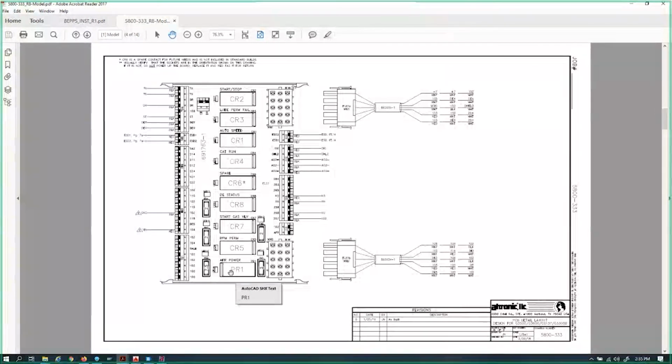Please note that if you run into a panel with this board in there, this is that 10 amp relay cartridge. Remember last week I was showing you the icons on these. All of these other relays have an icon on them that shows it as a double pole, double throw. This has an icon on it that shows it as a single pole, double throw. It is 10 amp, cannot be used in place of any of these other relays and vice versa. Damage can occur to the system, and certainly some problems with the system, if you put one of these relays in any of these other locations.